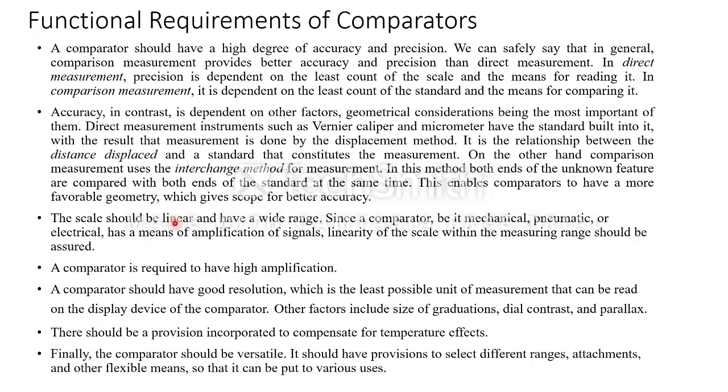In a similar way, in an electrical or electronic comparator, you will be using op-amps for amplification. It doesn't mean that you should use more op-amps so that you will get an accurate result. It's not like that. Whatever your application is, you should choose your op-amps accordingly. So you have to compromise between accuracy and cost.